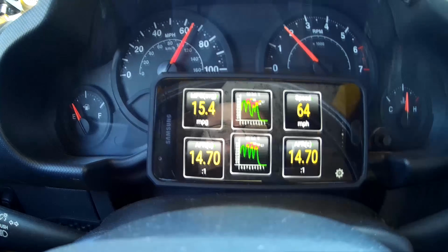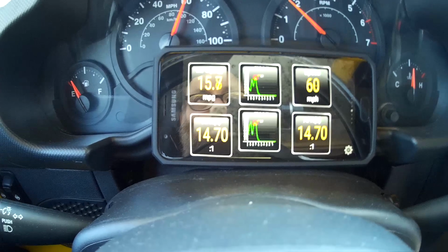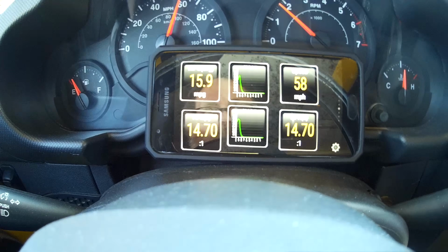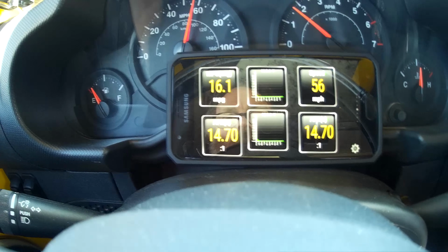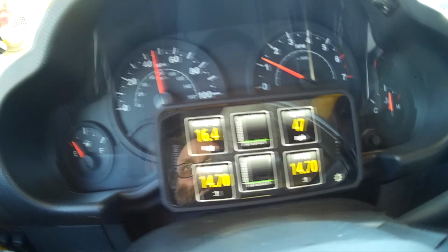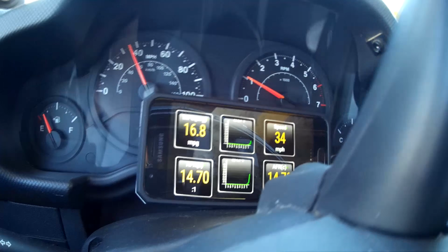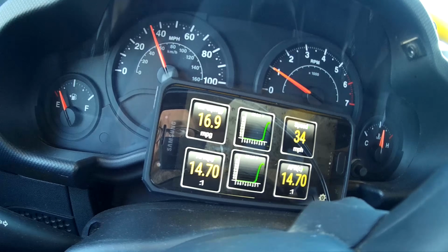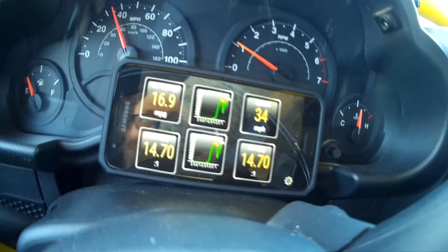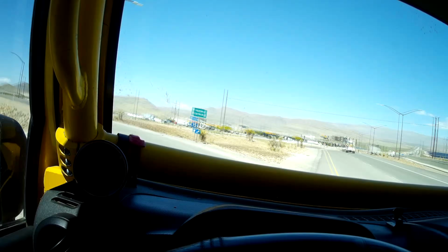Now we're going to try to catch deceleration fuel cutoff. Here we go. As you can see, the injectors are shut off. We flatlined to 0 volts, which is lean, and you can see our economy coming up. Now, after I slow down, it's going to have to keep the engine running, so you're going to see those injectors kick back in. There you go.